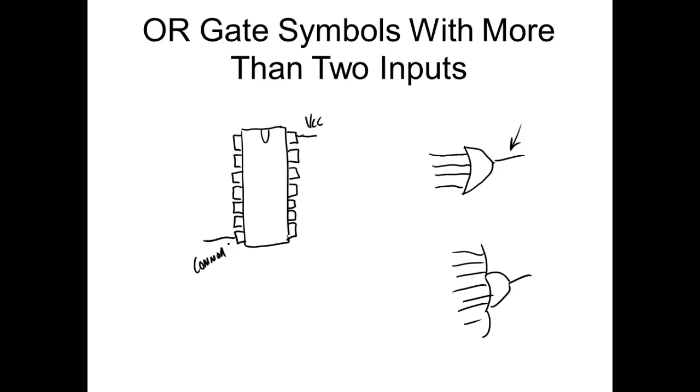So what would be the maximum input a gate could have? Inputs? I say 11. That would be the maximum because you got 12 pins, one for the output, right? You understand? One for the output and then 11 left over for the input. That would be the biggest we could probably have. If I use 2-input AND gates, then we could have a maximum of 4, right? You understand? So it all varies.